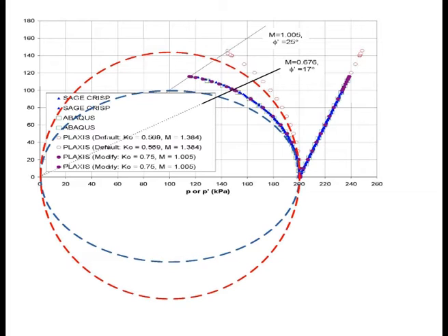The Soft Soil model in Plaxis consists of two envelopes. The first, on the left side, on the dry side, is the standard Mohr-Coulomb envelope. Then on the right side, on the wet side, they couple it with the elliptical cap surface. Now, this is where the catch is. The Mohr-Coulomb part is not the issue, because most soft soil will be far to the right, so you'll be following the elliptical cap surface.